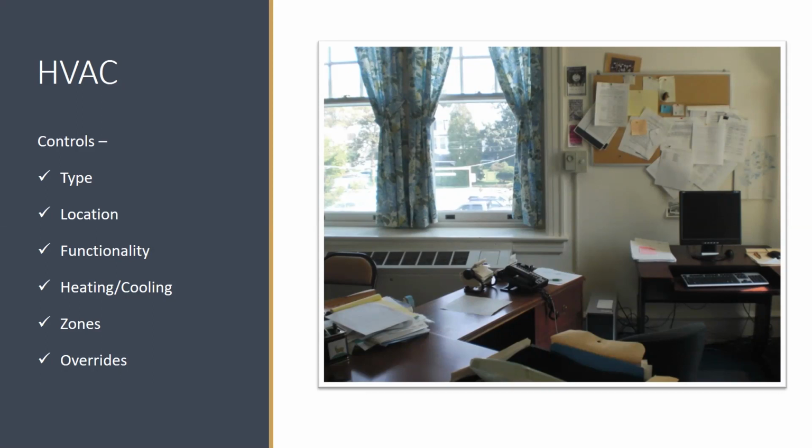Check out this photo. It represents a number of opportunities. First, we have a heating system. Below is single-paned windows, so the heat is going out the cracks through the windows. The thermostat is next to the heating system on an exterior wall. These poor occupants, they're never going to be warm.